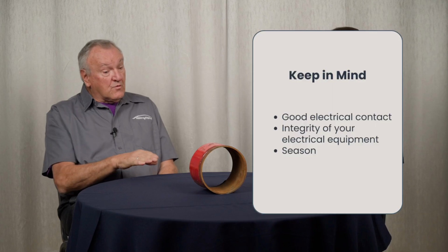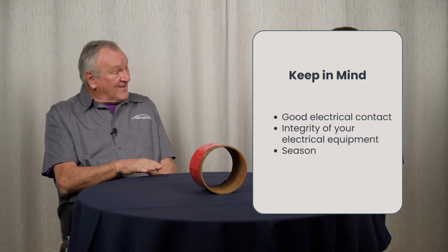Yeah. You're rolling these cables out and rolling them up and putting them out and rolling them up. And the connections break. And that is one of the most important things, is to ensure the integrity of your measuring equipment, and then also to note the season during which you're doing the measurements. Yes. We've had situations, particularly in the Eastern Cape, where the soil resistivity changes by several orders of magnitude between the dry season and the wet season. So you do a survey in the dry season, you think you've got non-corrosive ground conditions. Come the wet season, you've got a very, very different situation.